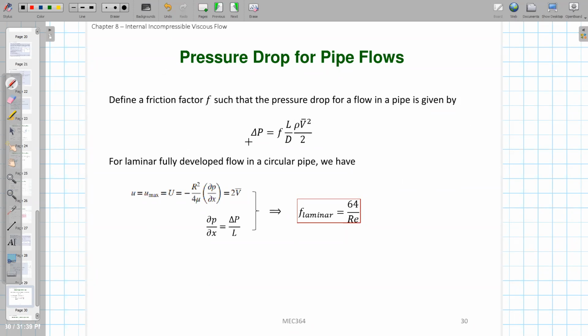Regarding the pressure drop, based on what I introduced, it will include several components. One component is the pressure drop we obtained before, due to the viscous force: even if the tube is smooth, we still have that pressure drop. And there are other components like the roughness component and so on. For the first component, due to the viscosity of the flow, even if the tube is smooth, we can define a new parameter called the friction factor, F, to calculate the pressure drop.